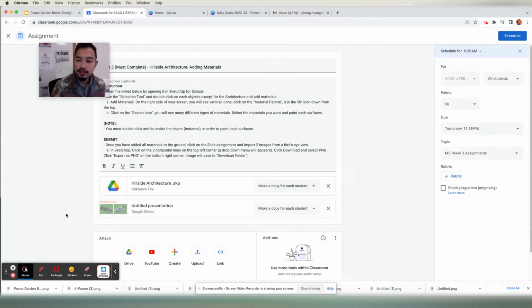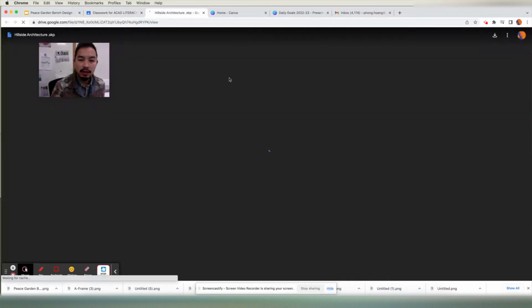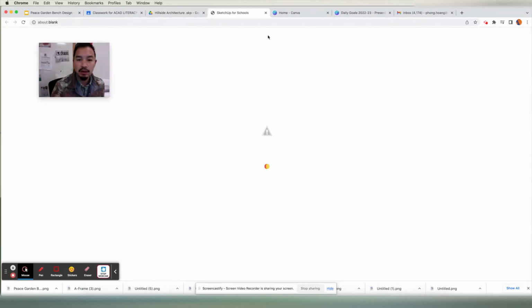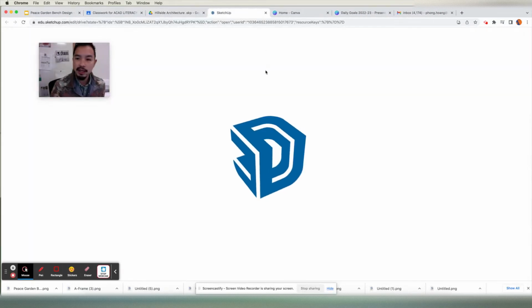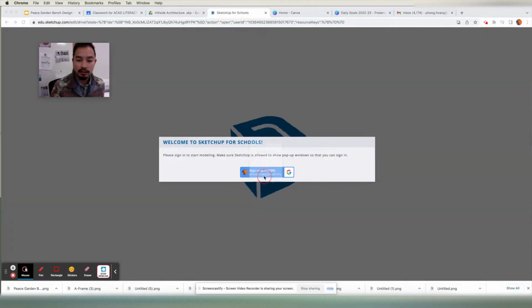In this session, I'm going to introduce to you our new site for our new project. To open the site, you click on this particular assignment here. It says Hillside Architecture.skp. That's the SketchUp file. If you click on that, go on top to the middle, click on Open with SketchUp for School, and you're going to sign in with your OUSD account.